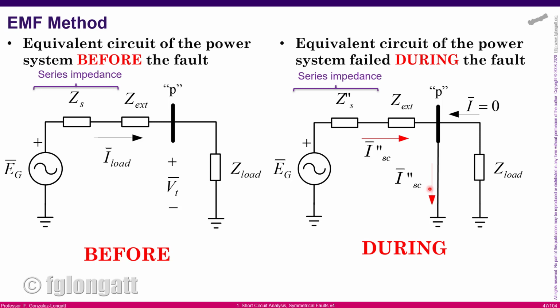During the fault conditions, remember something, I need to explain this for clarifying something. Those models represent a line-to-neutral representation, okay? We are talking about symmetrical and balanced three-phase systems, and as a consequence, we can use the single-phase equivalent model to work with quantities, okay?